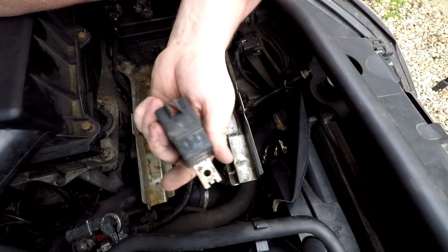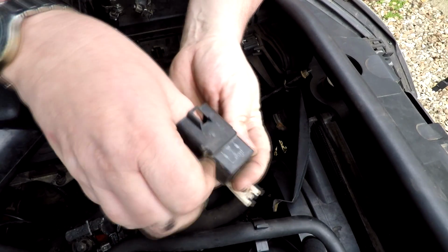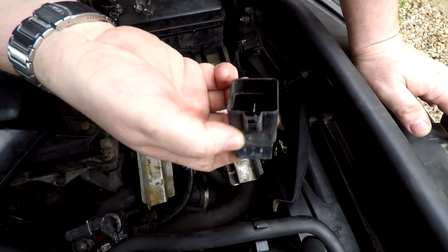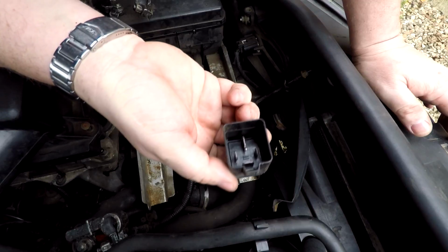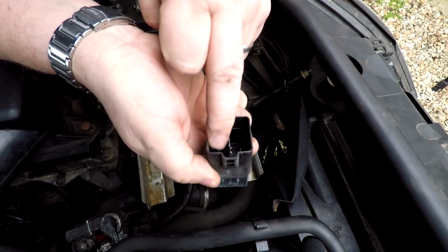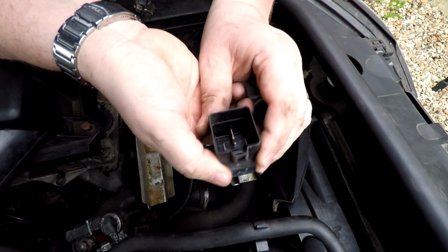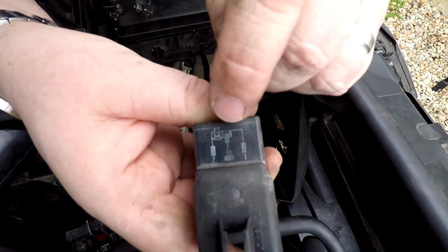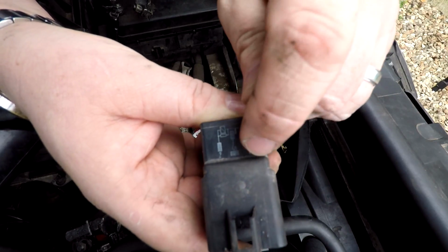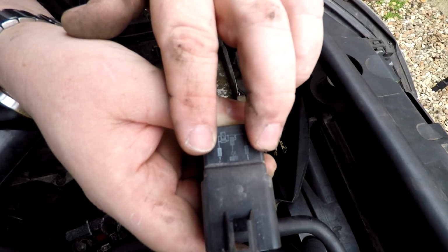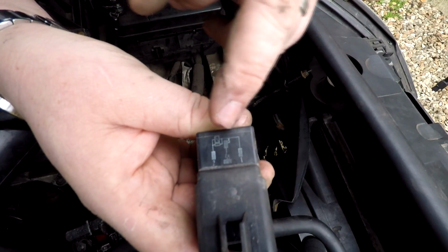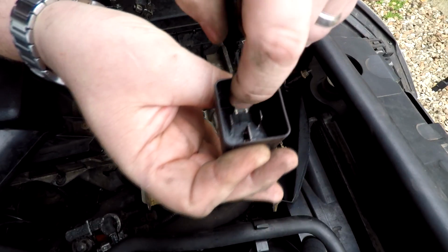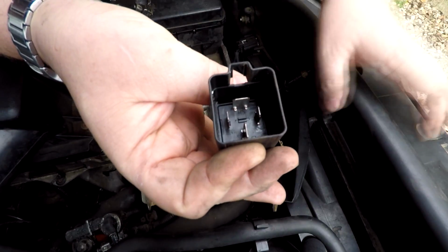So it has got a wiring diagram of the internals. Terminals 1 and 2, I would suggest, are the coil voltages. So if I had applied a voltage across terminals 1 and 2, that should bring in terminals 3 and 5, as you can see there. 3 and 5, there's a switch. So when you put your feed on 1 and 2, or your 12 volt supply, that should close that switch and put a feed from number 3 down to number 5 down there. So 3 and 5 are the ones that carry the load, and that's what could be overheating them terminals there.